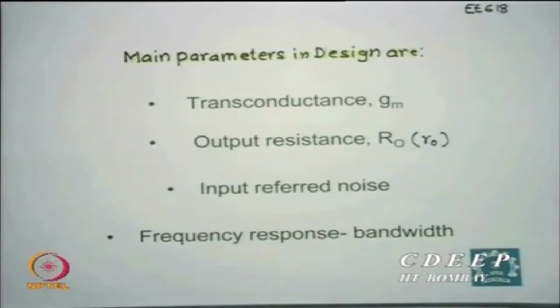What does that mean? From the input voltage, how much the output current gets modified by the input signal, essentially called transconductance. Okay. Voltage to current converters are essentially transconducting. So the first and most important parameter for an amplifier is the GM, transconductance. We will see what values we get in real life. Then the next very important characteristic of an amplifier is the output resistance.